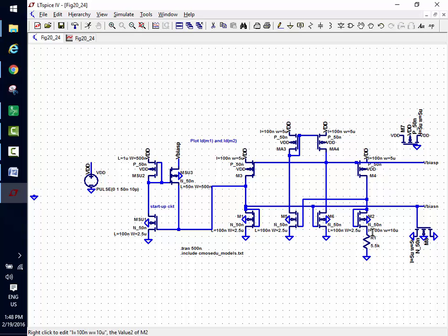Okay? So don't bond out your resistor, because you'd be tempted to, because then you can adjust your bias current externally with a resistor. And people have tried that all the time, but now I've got so much text in the book about how that's bad and positive feedback that I haven't had an email probably in 10 years now. Maybe not that long. All right. So let's go talk about this topology.